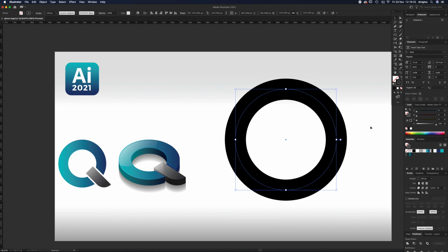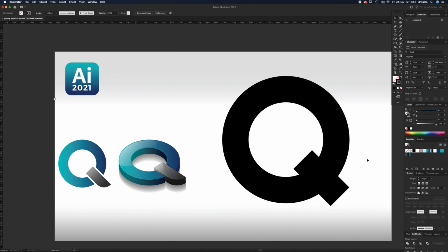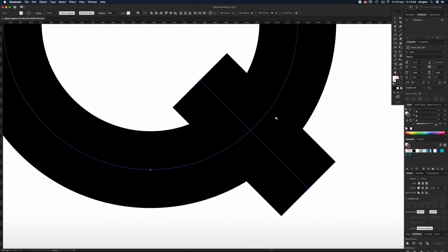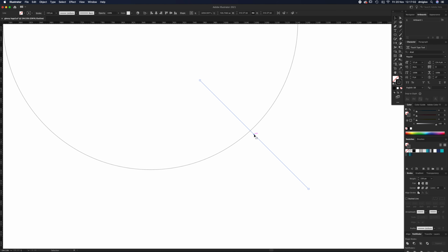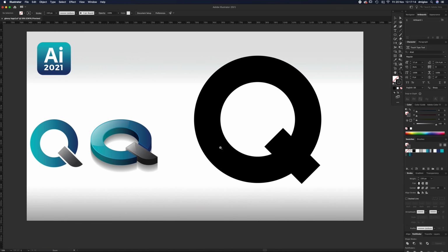With that selected, I'm going to go up to the line segment tool, and I'm going to click and drag holding Shift. That keeps it to 45 degrees. And I want something along the lines of that. Actually, I'm going to bump it back up to 150, so change that to 150. Yeah, that looks better. Now, if you zoom in a bit using Z and just select this line and press Command Y, you'll see I want that center point there to be over the line. So I'm just going to use the cursors and move it up there for now. Press Command Y again. That looks fine.